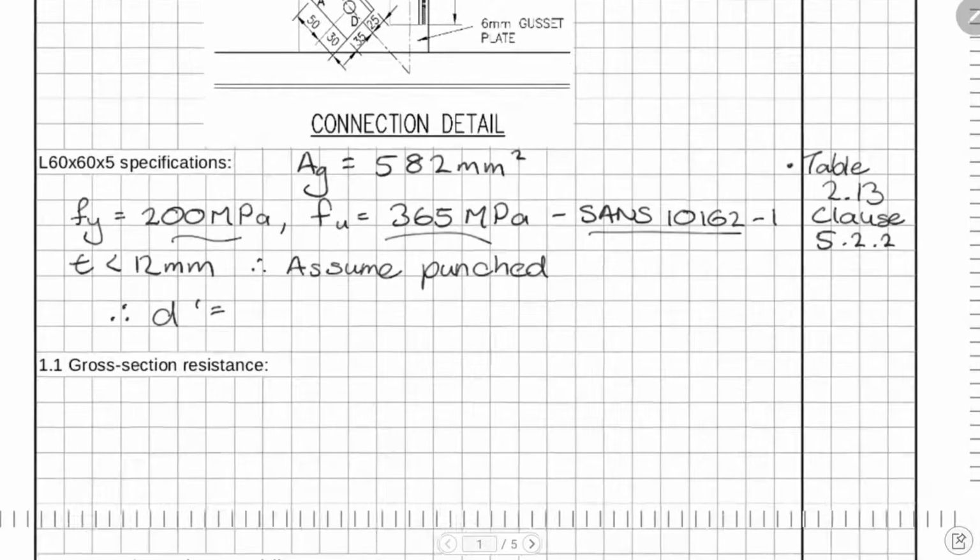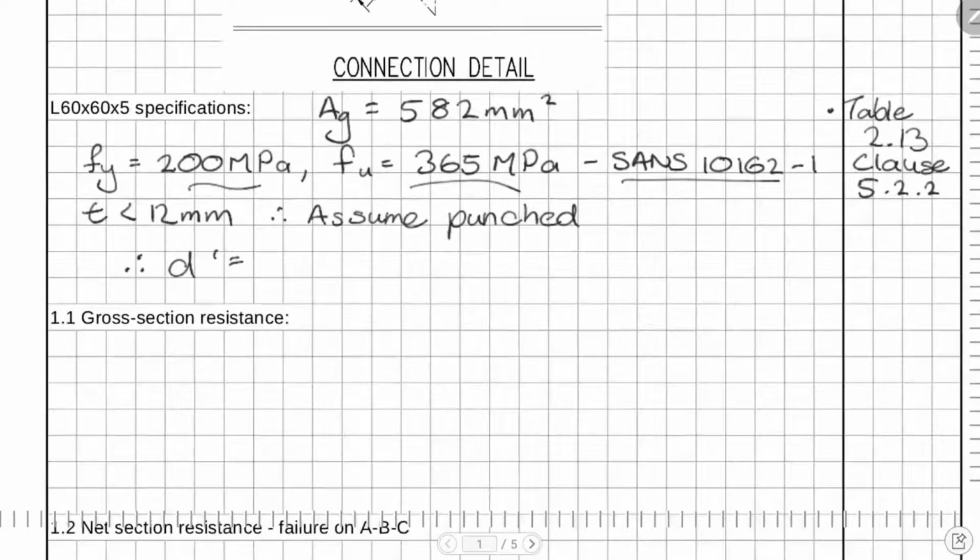And we need to know how big is the effective bolt area. How much material do we lose due to the bolt? In a factory somewhere they manufacture this, and we don't know exactly what machine they will use to put the hole in that piece of steel. They may either drill it or punch it.